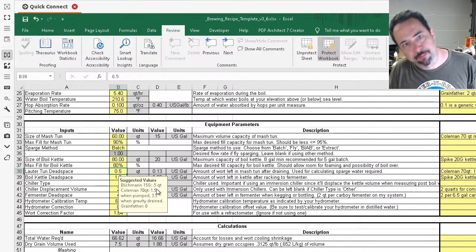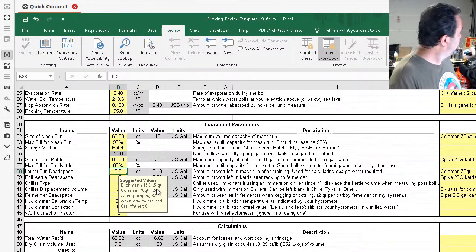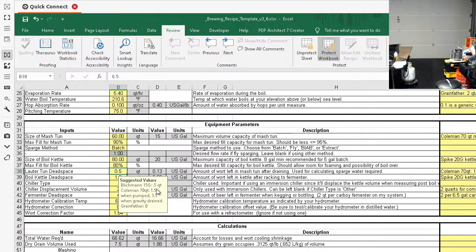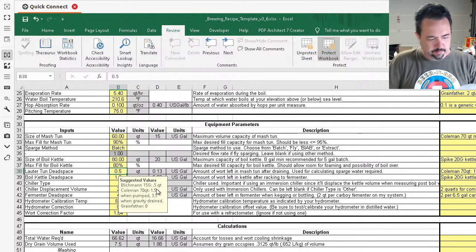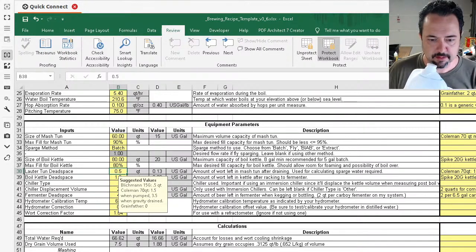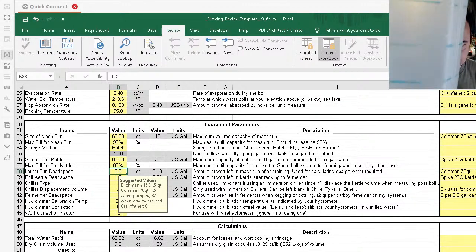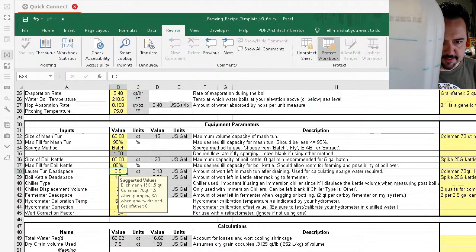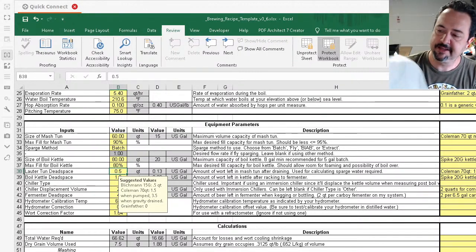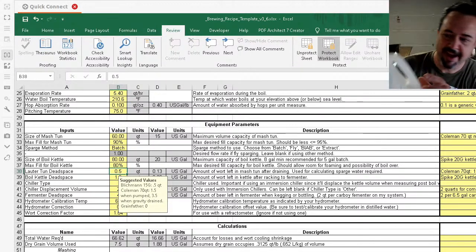You open your valve, you pump it out, drain it out, whatever you want to do, and the volume that's left, you pour into a measuring vessel. Now I do have one here. Hold on a minute. So this might be a little overkill, but I have a milk jug here. I hope you can see this. Hold on, let me check my screen here. Milk jug here, where I've measured increments on this thing, and I have it calibrated for 68 degrees Fahrenheit, and I use this for that purpose.